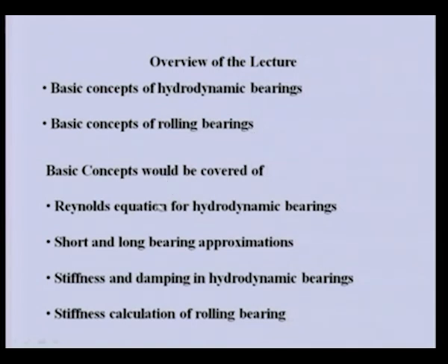For the bearing, we will introduce the Reynolds equation for the hydrodynamic bearing, and for short bearing approximation or long bearing approximation, we will see how to solve this partial differential equation in closed form. We will also give a brief idea about how, if the bearing is finite, the Reynolds equation can be solved using the finite difference method.